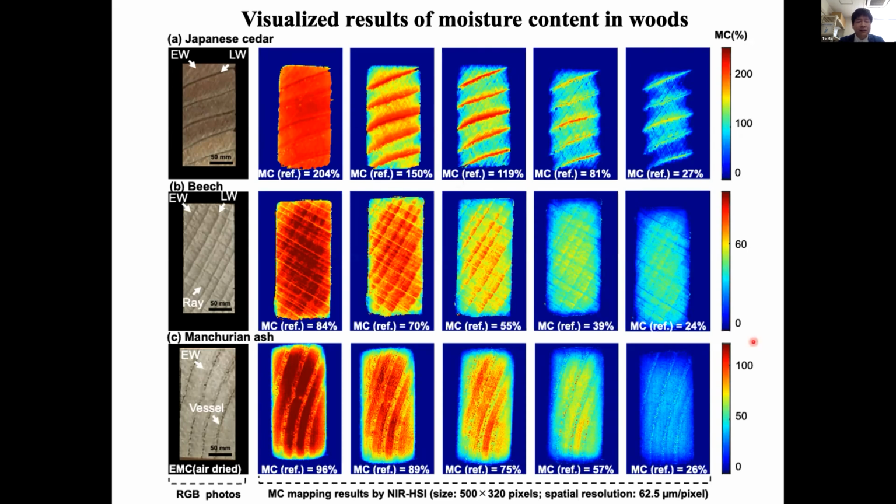It is evident that the early wood part had more water compared to the later wood parts initially. This could be caused by the thin wood cell wall in the early wood parts, which has a larger space in lumens. In addition, the edge of each sample was the first to dry, and the late wood part dried last because of its strong water absorption capacity.